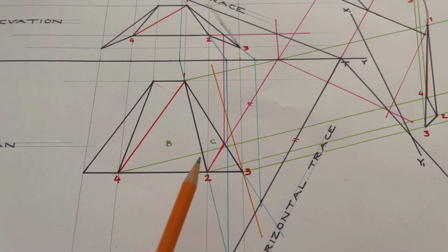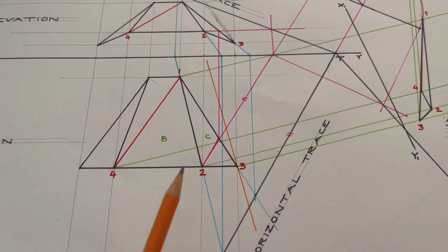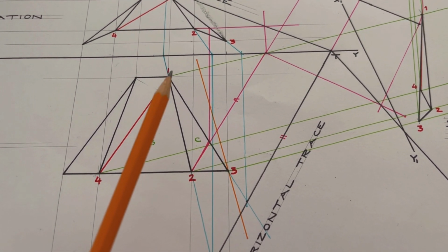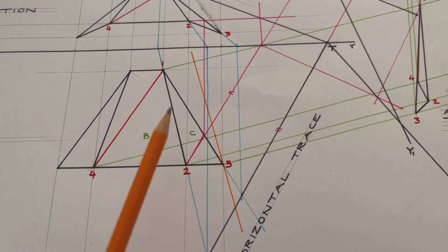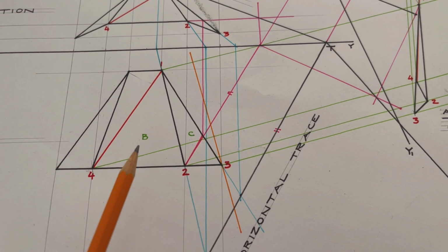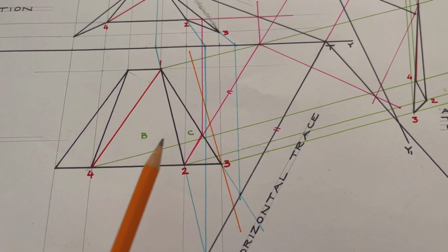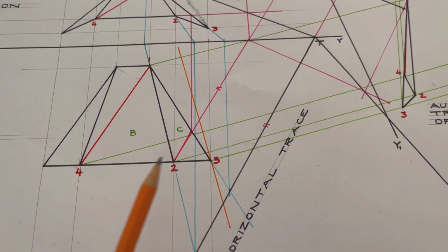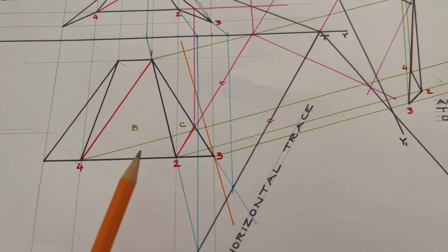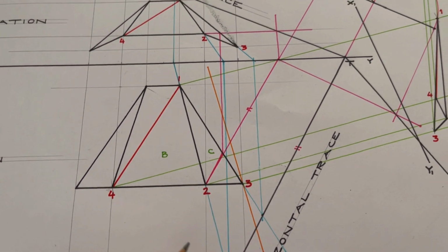Now, if you look along the true length of a line on a plane, the plane will project as an edge. So because this line is common to B and common to C, if we get the true length of this line and then look along that line, B will project as an edge, as will C, and therefore we will get the dihedral angle, because we'll be seeing both planes as edges. This is how this method works.